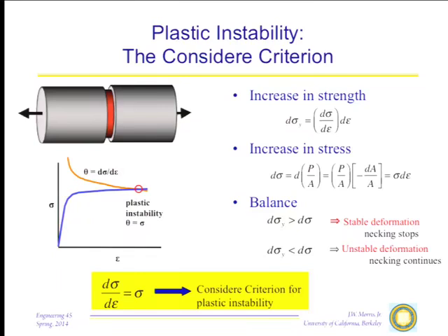In fact, that little strain will normally be at 45 degrees to the axis of the bar, but I've drawn it this way because it's easier to visualize and to calculate. One of two things will then happen once that little increment of strain forms. Think about the consequence of that. There are two consequences of this little increment of strain. One is that because the strain happens, the material gets stronger, because the material is always work hardening, or getting stronger, as we continue to strain it.